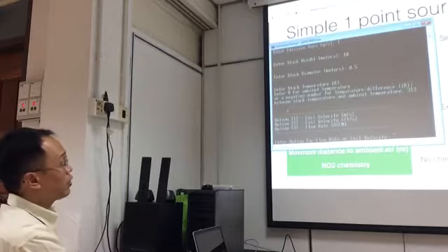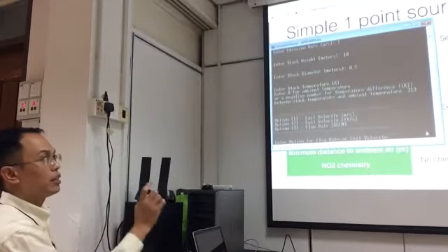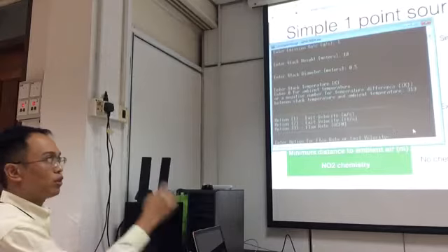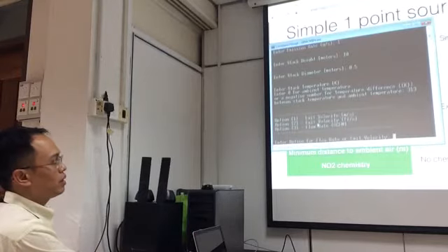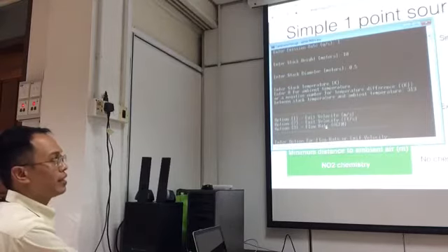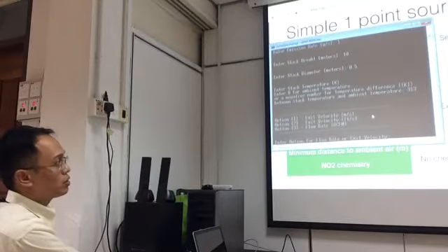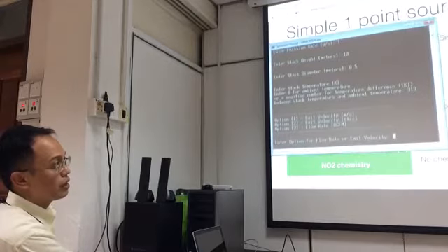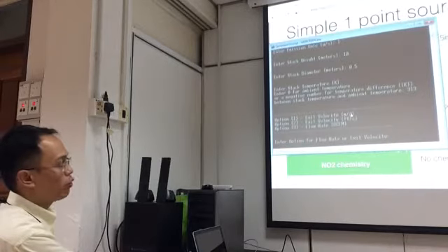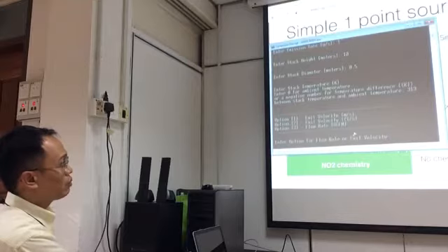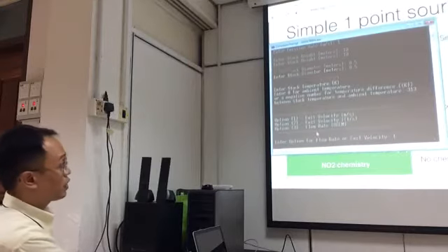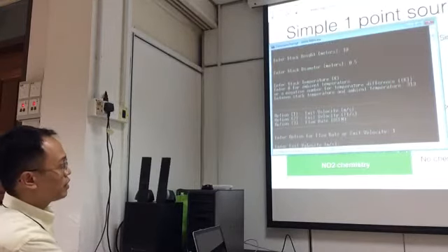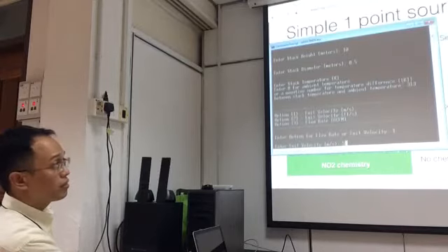And then how do you want to input the emission rate? Is it exit velocity in meter per second? Is it exit velocity in feet per second? Or maybe the flow rate in ACFM, actual cubic feet per minute. So we use the SI unit. So we use the exit velocity here for the m/s unit. So option number 1. Press enter. What is the exit velocity in meter per second? 5.